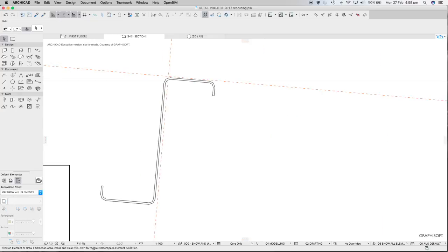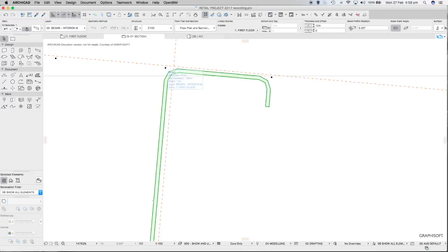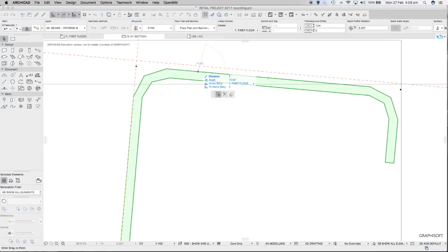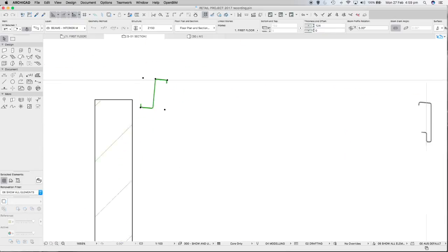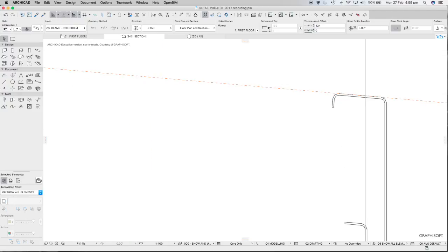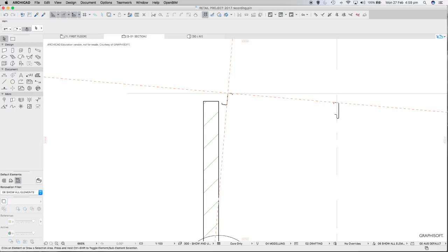and then if we move this, drag from that edge, go to drag again, and drag that edge to there, but then drag it again in case it has moved off until it goes perpendicular there. So I want it to be in that corner of those guidelines, and that guideline was 1350 from its mating point over here. So we've got a 1350 spacing for our first purlin now.